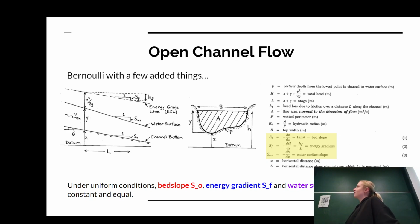This is a diagram that we adapted from something you might remember in fluid mechanics. On the left-hand side, you see we've got our z's, we've got our y, and we've got our v squared over 2g. Does anyone remember what Bernoulli looked like from fluids? Z plus P over rho g, or gamma, plus V squared over 2g. Nice. So we're taking Bernoulli and adapting it for open channels.